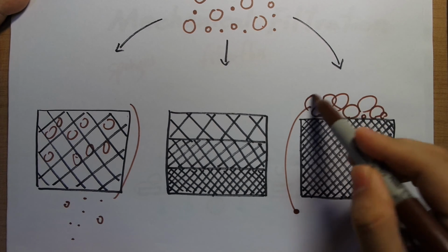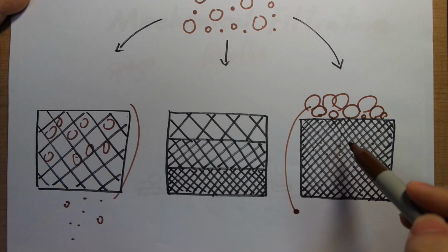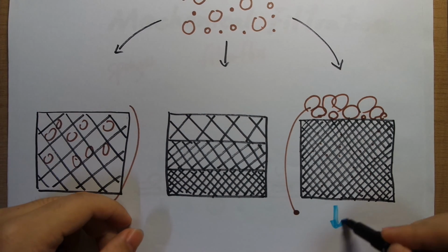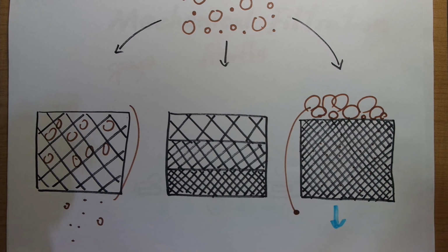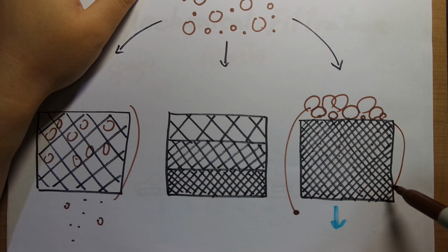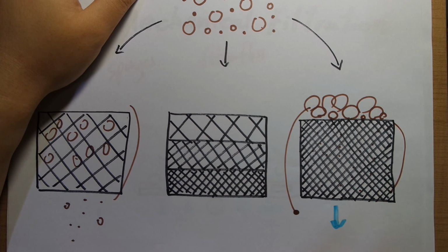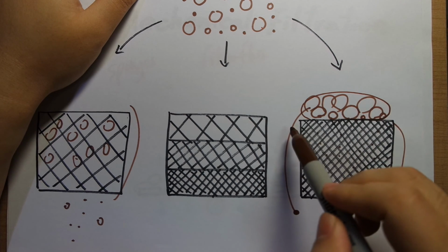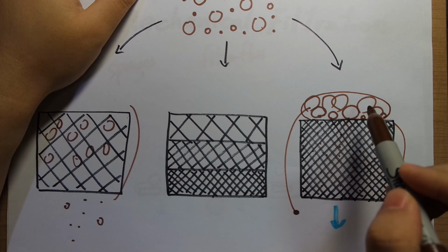They are not able to enter. So in the end, you get, well, clean water. So it works, right? But the problem is, this will be much higher maintenance, because you're not utilizing the full space you have to filter out all your solids. Instead, the large stuff is getting stuck out here, and this will clog your filter fast.